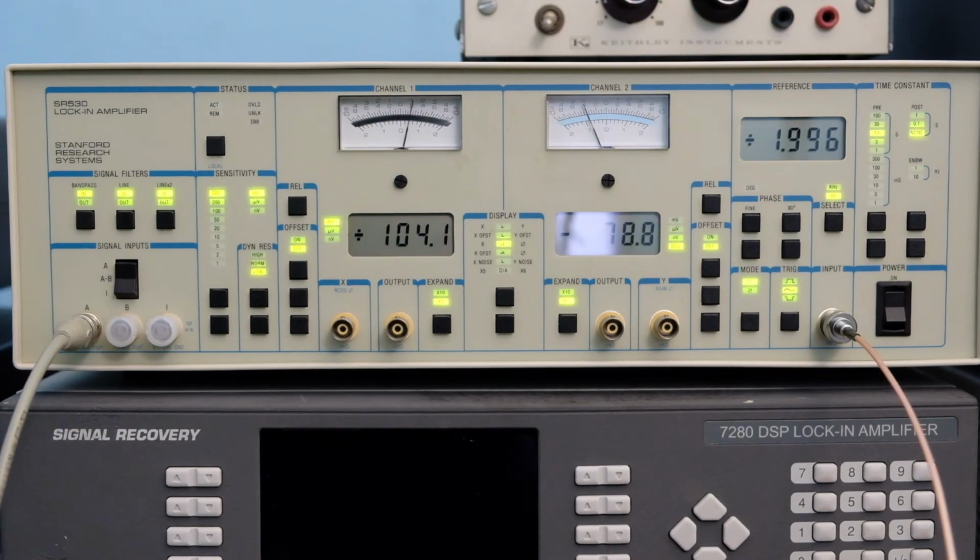Just to make sure that my setup is working, I connected this 6.8 millifarad capacitor at this same frequency, 2 Hertz, and now you can see that the amplitude of the signal is about 104 millivolts, and the phase angle is around minus 79 degrees. So these numbers will of course give a much more realistic value for the ESR and capacitance value, and I will report those after I do the calculations.